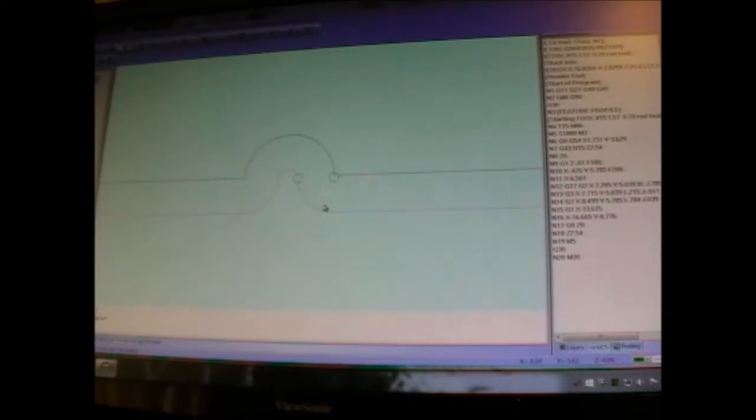The toolpath is forming 3 arcs, an entry arc, this arc, and an outward arc. Let's look closely at this because we need to understand the formatting and how it's defined in order to be able to convert it from an XY toolpath to an XZ toolpath.